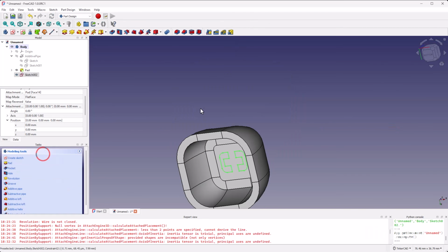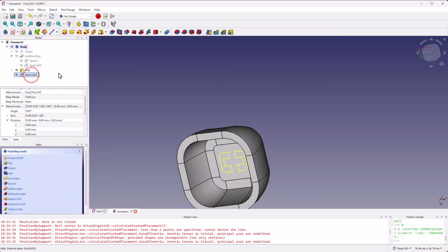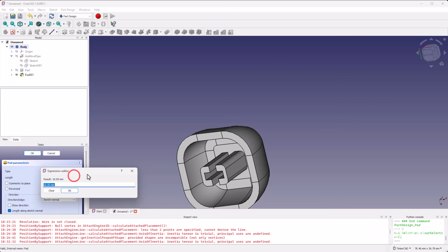So click close. And remember, we wanted that 1 millimeter gap here. So we're going to set that parametrically as best as we can. So select the sketch, select your pad. Let's go to the equation editor. Let's go with that first sketch. We're going to go into the constraints. We're going to get the height, which was 10 millimeters.